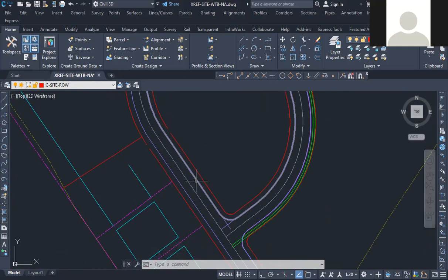Okay. Really, the last piece of information you're going to need is going to be your house and your driveway. We'll do that if we have time. But what I want to do today is show you how to label your lot areas and your metes and bounds, the geometry of the lot. Okay. It is all done with annotations. The same way you labeled those contour lines, you're going to label the property lines, the lot areas, right? They're different annotation styles.